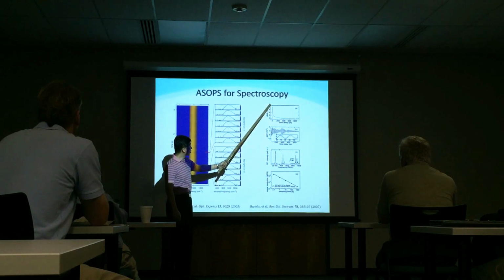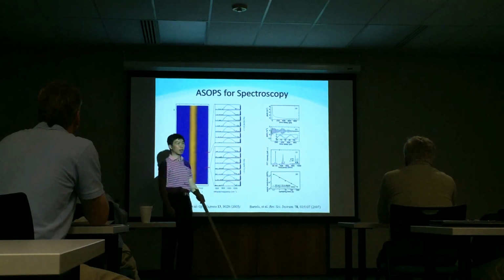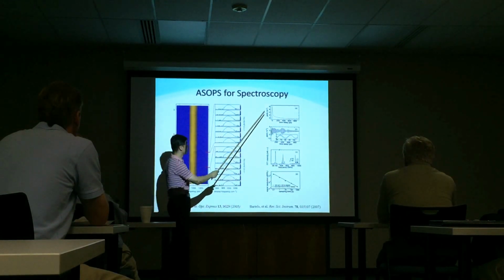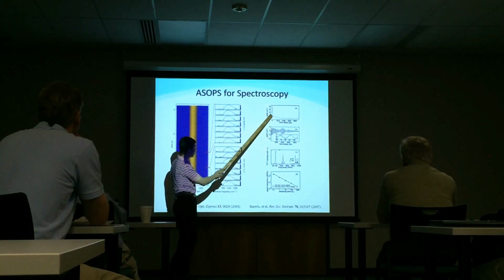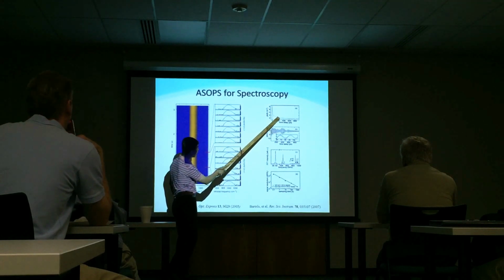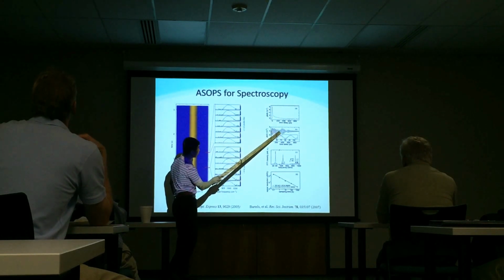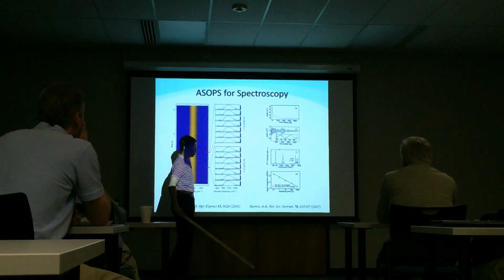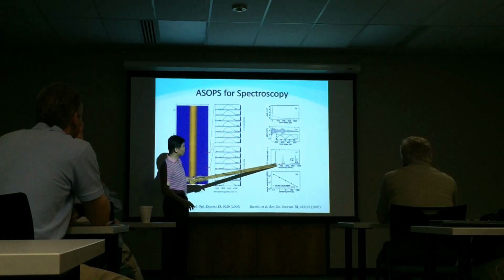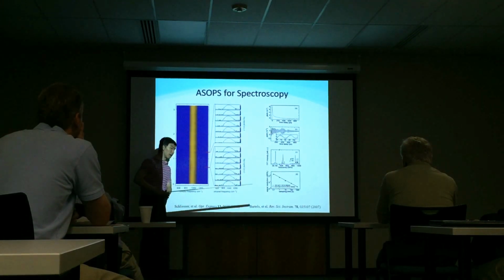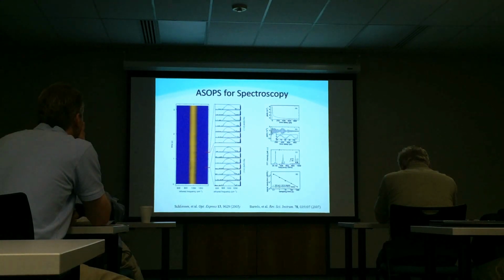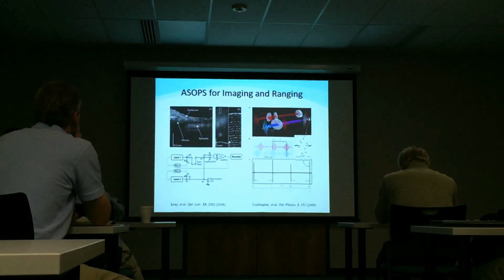So this is the impulse, okay, at time 0, and then you probe the response of the system, based on time. Okay, so then what they can do is they zoom in on part of that. They can detect these very fine oscillations, and then you do a Fourier transform of these oscillations. You can see the features, and so you can derive some properties of the device based on these measurements.